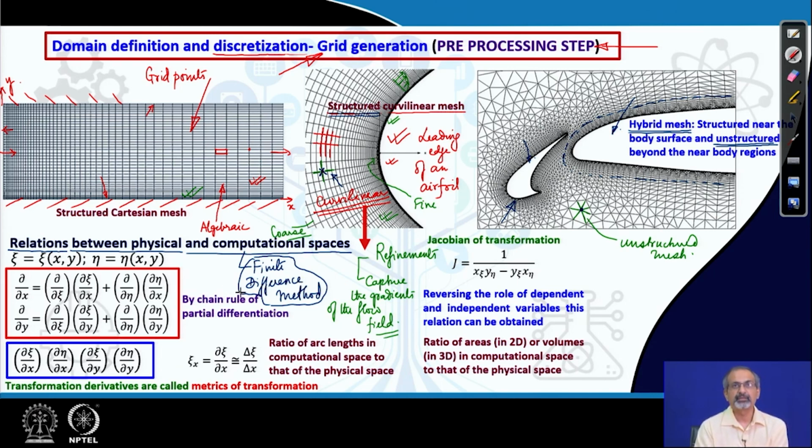While in finite difference method, you try to transform the problem from the physical plane which is curved to a computational plane which is nice and rectangular, let us say, where we have uniform grid spacing. That is why we transform the problem from xy plane to xi eta plane. So, the xi eta plane is basically the transformed plane. When you do that, all the governing equations have to be transformed as well. So, you have seen that in governing equations we have derivatives, partial derivatives with respect to x, y and so on. So, each one of them would have to be transformed.